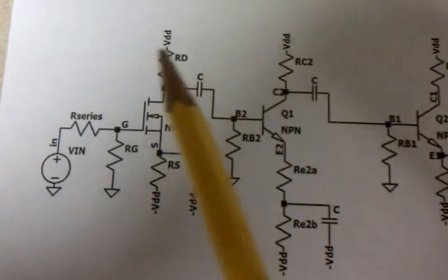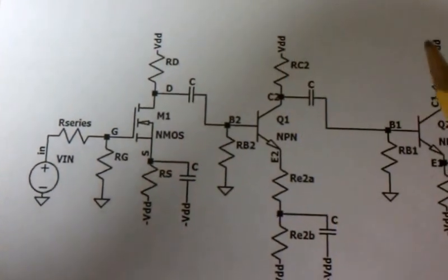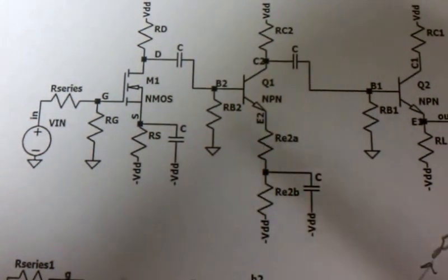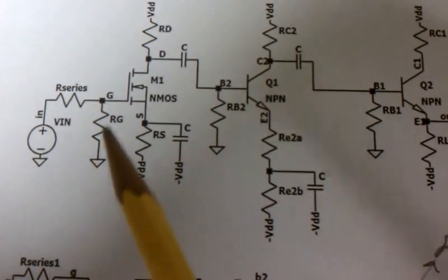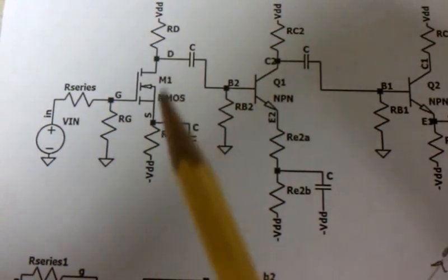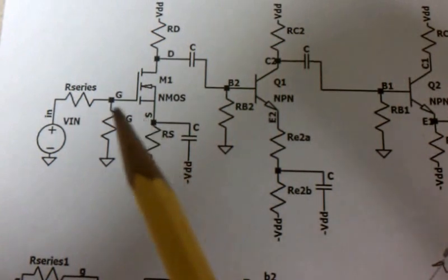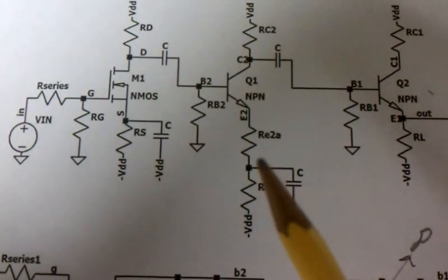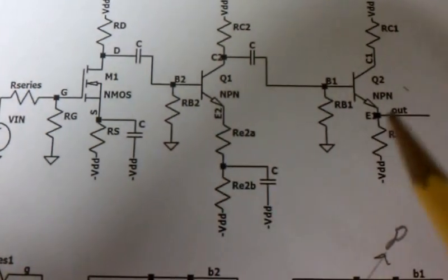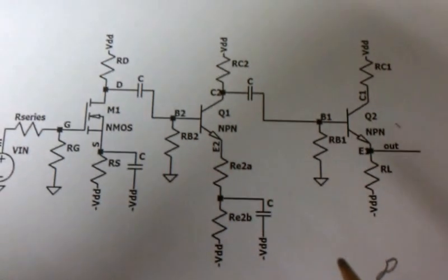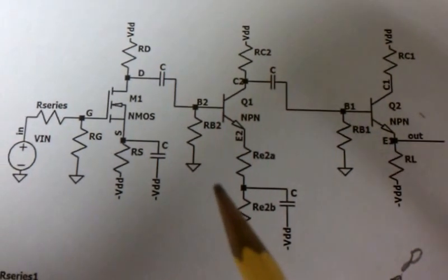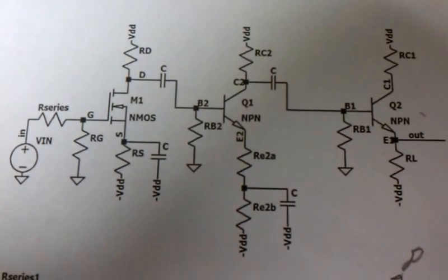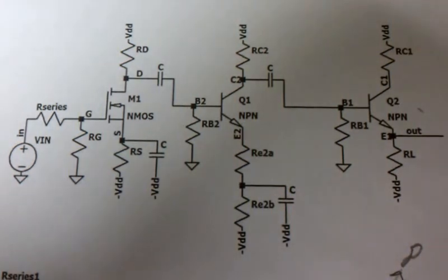Okay, so that's okay. The voltage supplies are all positive here, negative, negative, negative, negative, negative, so I haven't made a mistake there. This sets VG at 0, but with the drain current flowing here, that should put a VGS that turns the transistor into saturation mode. Same thing here, except it would be in forward active. Looking through, I don't have any other concerns where maybe I've made a mistake in the circuit.